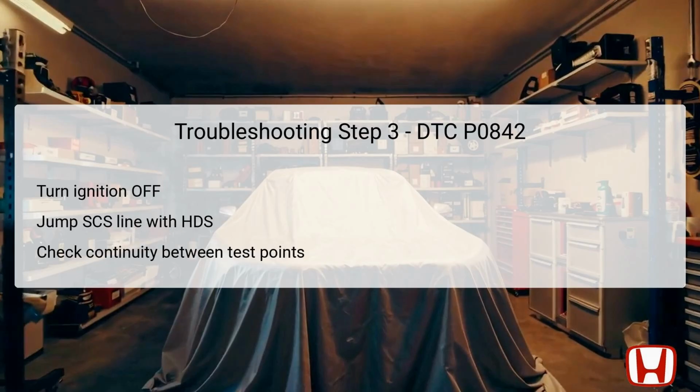The third troubleshooting step revolves around checking the wiring to uncover any potential shorts that contribute to the DTC P0842. Initially, turn the ignition switch to the lock position, effectively powering down the system. In this step, utilize the Honda Diagnostics System, HDS, to jump the SCS, Service Check Signal line, allowing for continuity